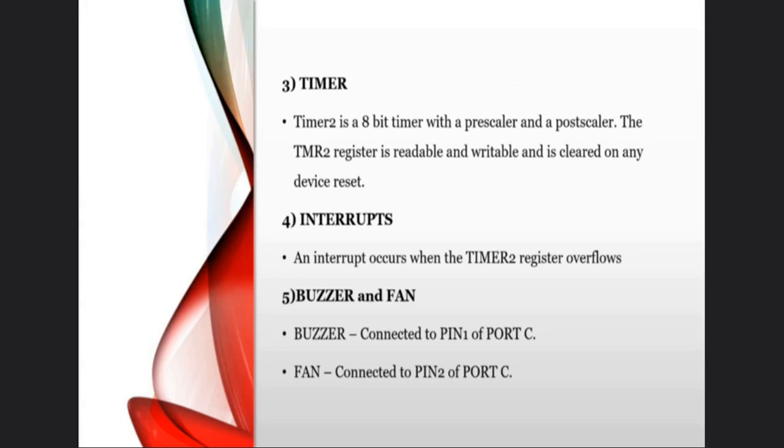If interrupts cannot be disabled even if we wanted, they are non-maskable, because non-maskable interrupts have high priority and they cannot be ignored. These non-maskable interrupts are again classified into two types, external interrupts and internal interrupts. If they are produced by external sources, then it is an external interrupt, and if they are produced by internal sources, then these are internal interrupts.